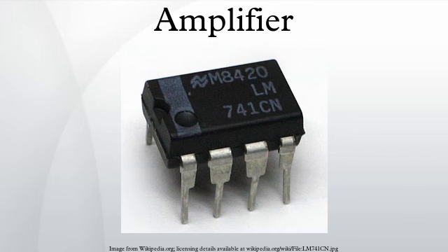Class C. Class C amplifiers conduct less than 50% of the input signal and the distortion at the output is high, but high efficiencies are possible. The usual application for Class C amplifiers is in RF transmitters operating at a single fixed carrier frequency, where the distortion is controlled by a tuned load on the amplifier. The input signal is used to switch the active device, causing pulses of current to flow through a tuned circuit forming part of the load.